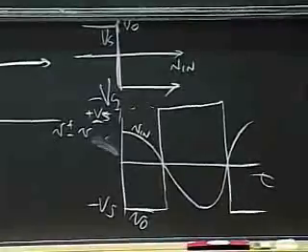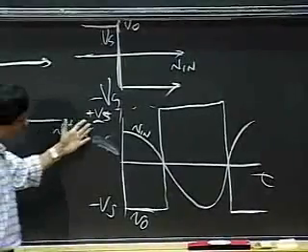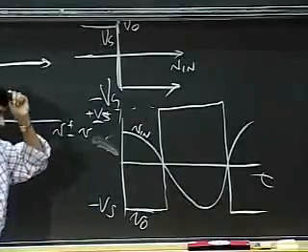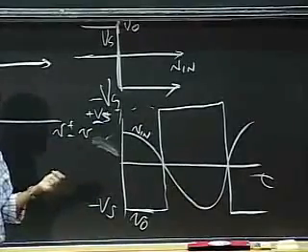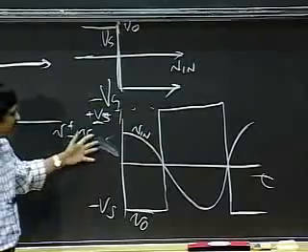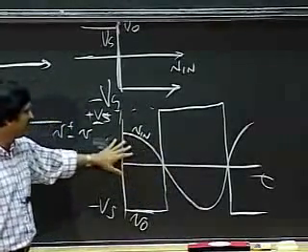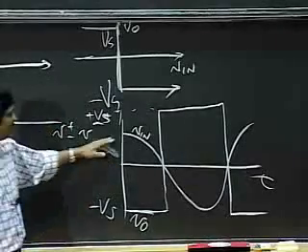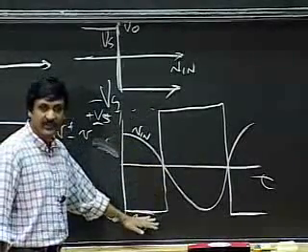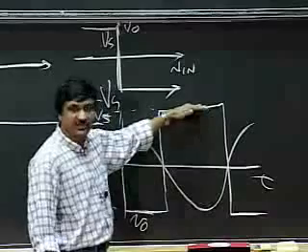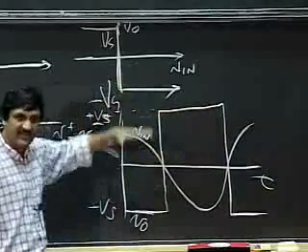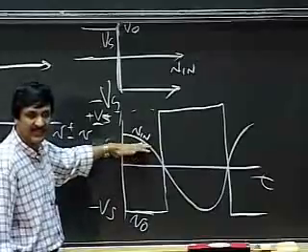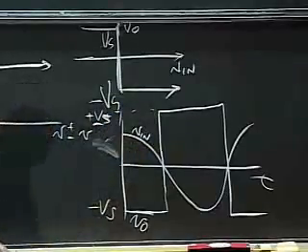So that's quite nice. Such a circuit is pretty useful to me. Let's say, for example, I want to build a little digital circuit that is fed ones and zeros. So I can use a comparator to turn my Vin voltage into a sequence of ones and zeros. When Vin is positive, I produce a 0. When Vin is negative, I produce a 1. So I can get this 1, 0, 1, 0 sequence coming out, corresponding to the values of Vin being greater or less than 0.